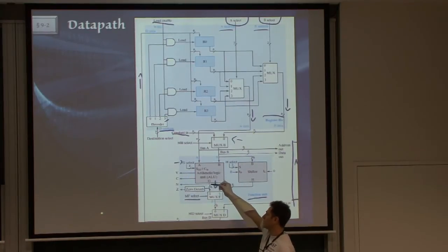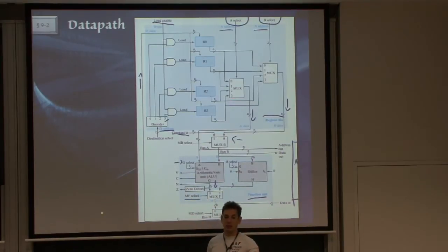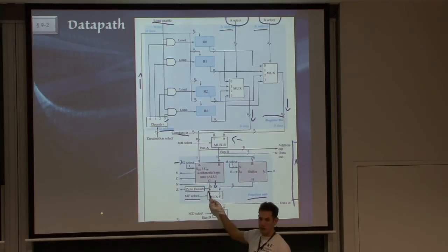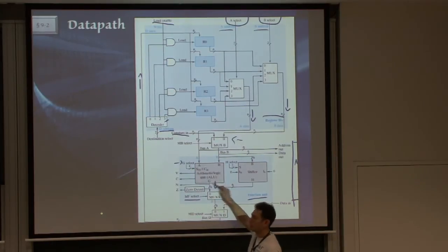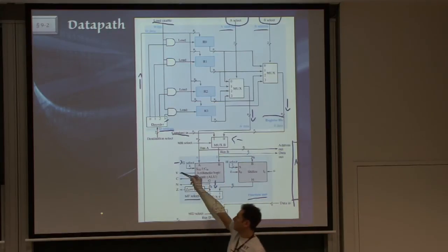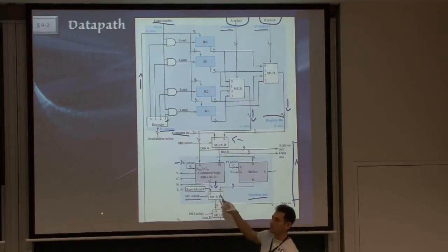So you see they're connected to the line coming out, because the negative is essentially the most significant bit of the sum. Zero is if they're all zeros. You don't actually need to know what happened here. But for the C and the V flag, these are direct outputs from the actual operation there. C is the carry, and V is the carry in and the carry out of the most significant bit. So that's why they're designed like this.